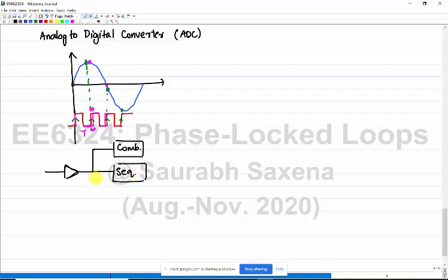So when you do all such kind of things, you have multiple circuits and you are feeding a clock here. Now, whenever you connect something to the buffer, this is a circuit block, right, you are going to add parasitic capacitance at this node.